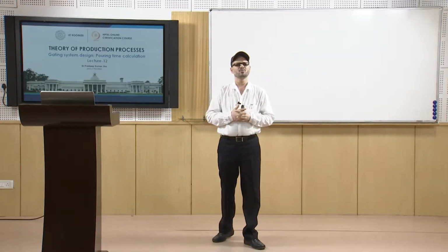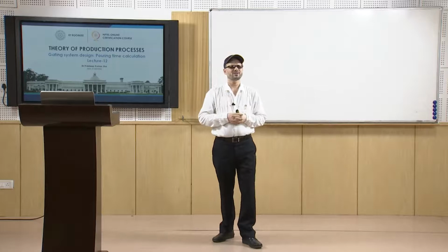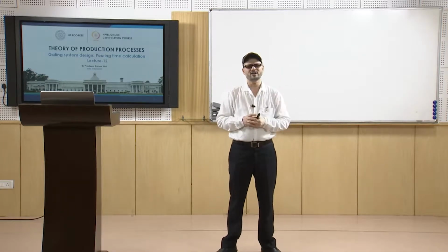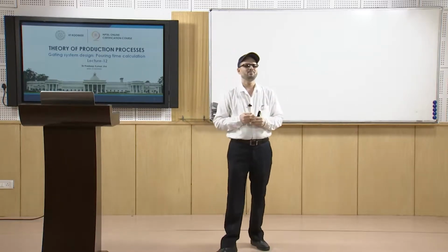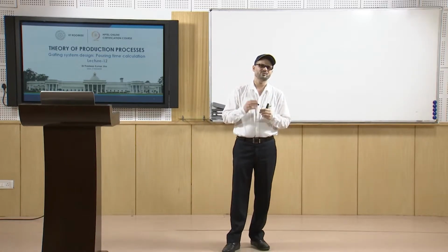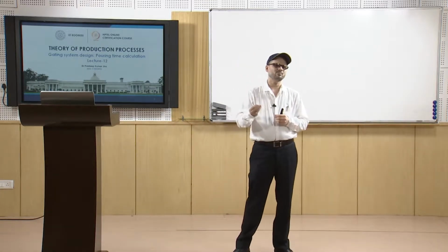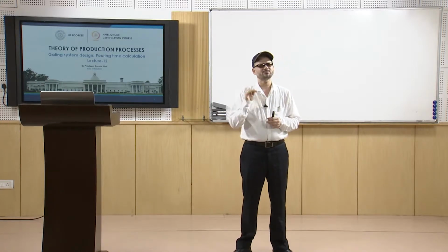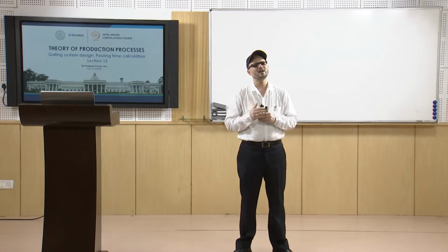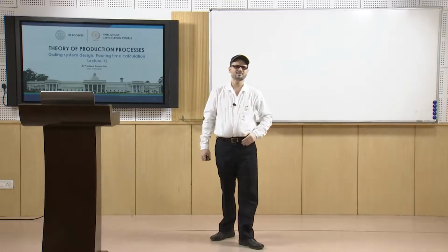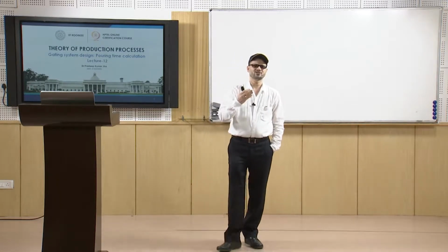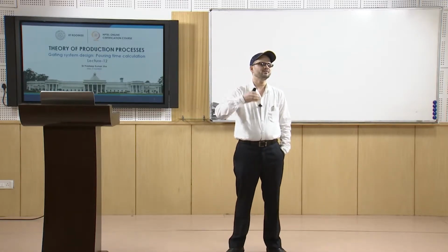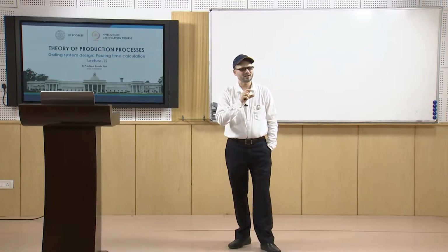If you have a permeable mold and the channel is not running full somewhere during the passage, and a condition is generated where the pressure is less than atmospheric, then atmospheric gases may enter that channel and spoil the quality of the cast, particularly if the cast metal is prone to oxidation or is a drossy material. That can be understood by reviewing